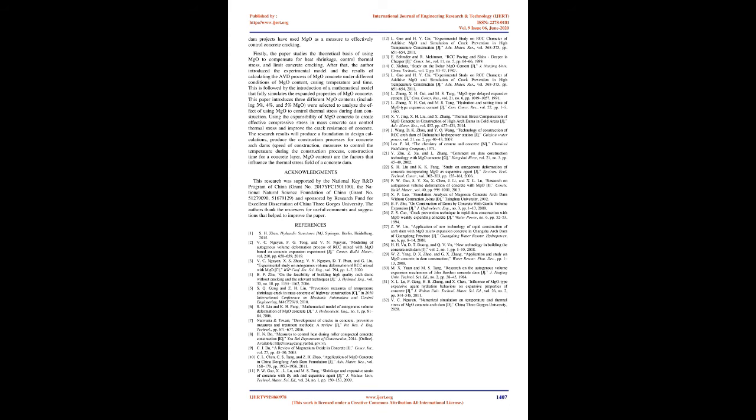This shows the effectiveness of using MgO to prevent cracking of concrete dams and control thermal stress. MgO can compensate the volume deformation shrinkage of concrete blocks, and is an effective way to solve the problem of temperature cracks in concrete engineering construction.